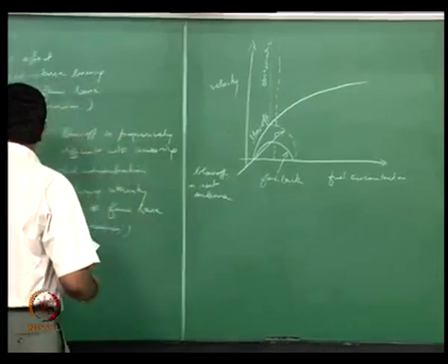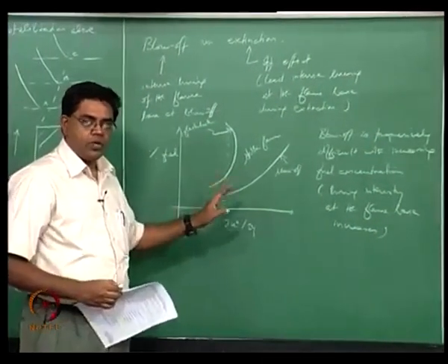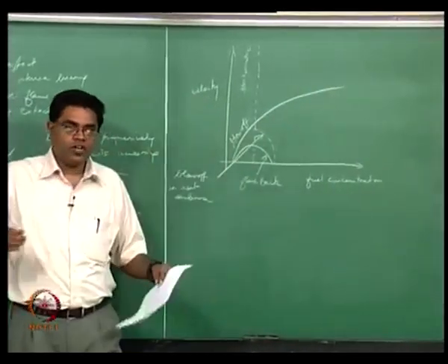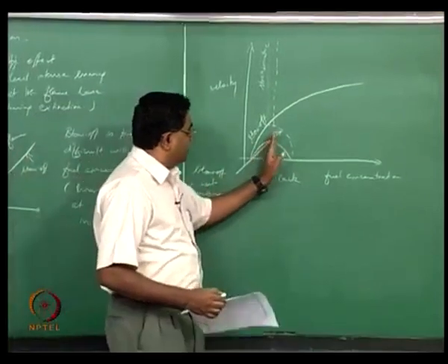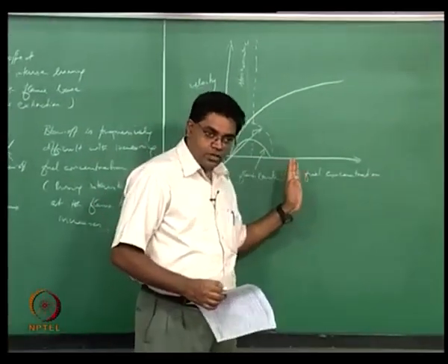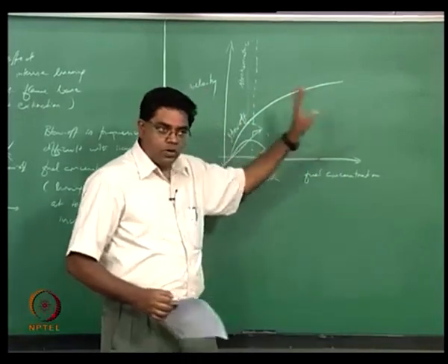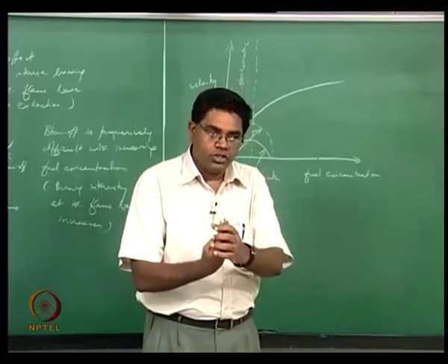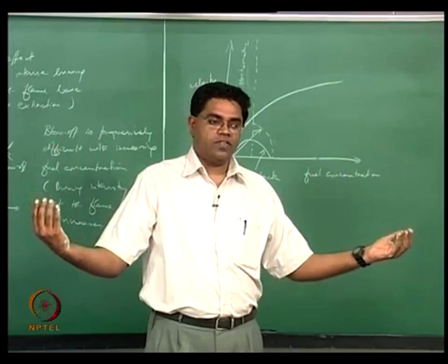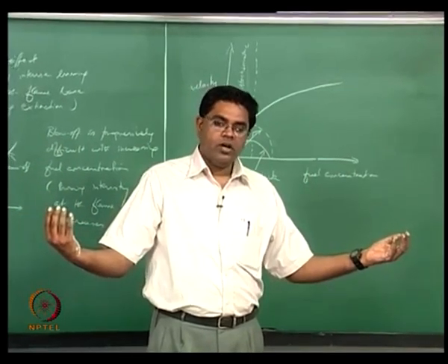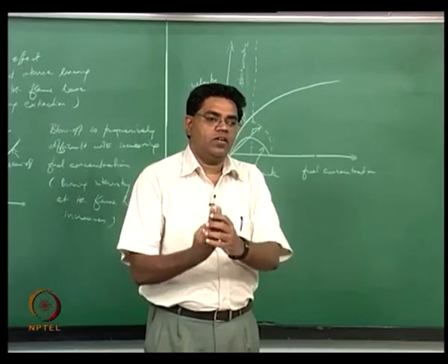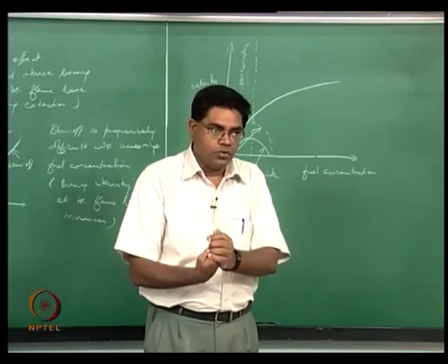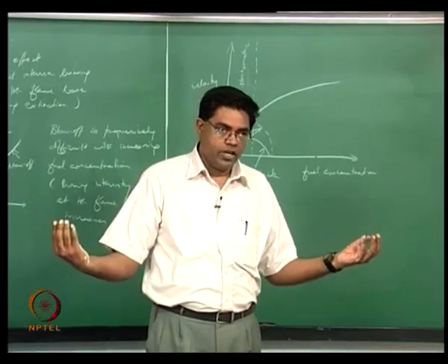So it's sort of like reproducing this picture, but then I would like to point out one more thing which is beginning to look very interesting for us now, and I would imagine you should start thinking about it right away. We are now beginning to look at a space which is significantly fuel rich, right? So if you're somewhere there, what you should be looking at is you're now having a lot of fuel that's coming in and only a little bit of oxidizer that's coming along with it, right, in an oxidizing ambience, right. What if I did not have any oxidizer at all here? It's highly fuel rich to the point of being only fuel in an oxidizing ambient. What would I get?